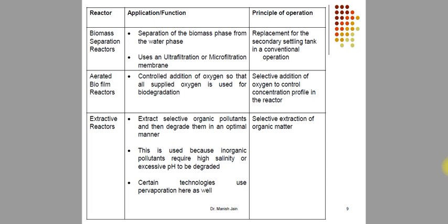During fermentation, what happens several times is that when the alcohol is produced, that alcohol itself acts as an inhibitor for the reaction. When a certain concentration of alcohol is achieved in the reactor, that alcohol will start to kill the yeast and the reaction will stop. So if you have a membrane reactor, then you can separate out the alcohol simultaneously with the reaction.